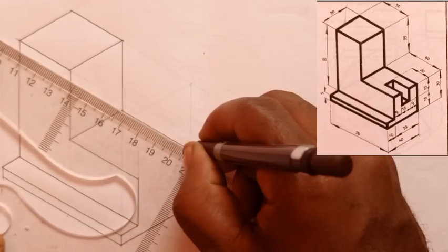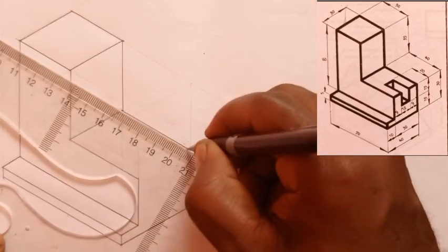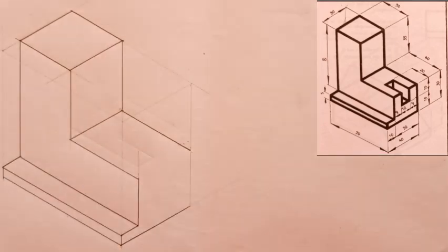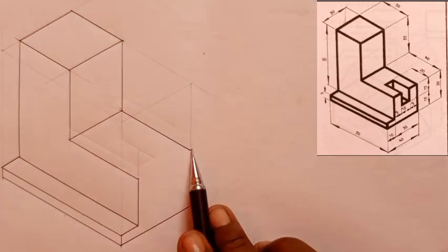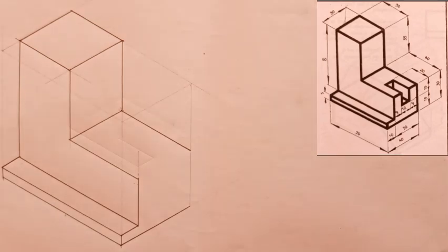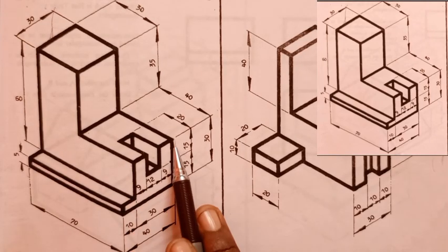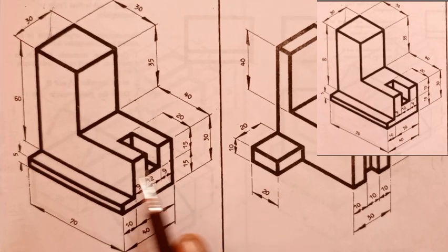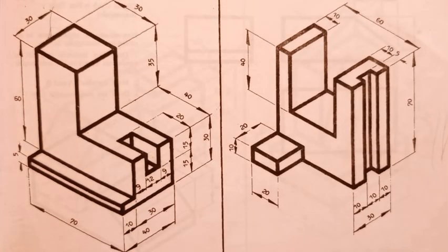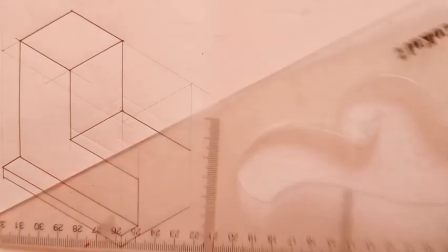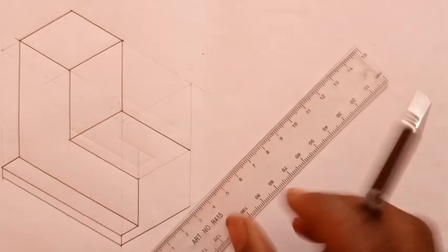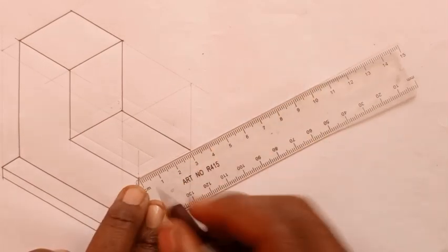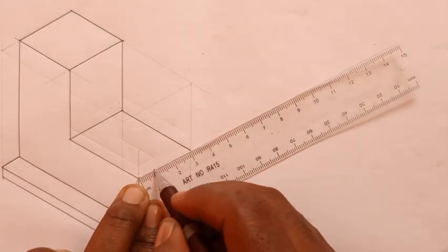Can you see that? That's what we have. Then from this point you are seeing here, from this point and this point here is this point and this point. So inward I'll measure 9, inward I'll measure 9. So let's do that. I'll just take my set square and I'll draw a line like this, faint line. Then I'll measure 9 inward. So if I take my meter and place it this way, from 0 to there is 9.